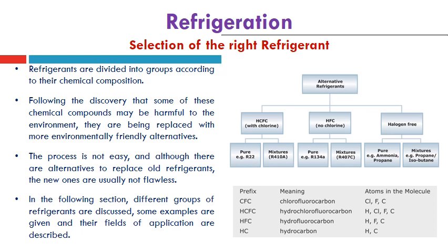However, hydrofluorocarbon also has no chlorine, if pure, such as R134A, or maybe a mixture of these HFCs such as R407C, that may affect the evaporating temperature stability inside the wet region, as can be seen on the presented p-h diagrams at the start of this lecture.